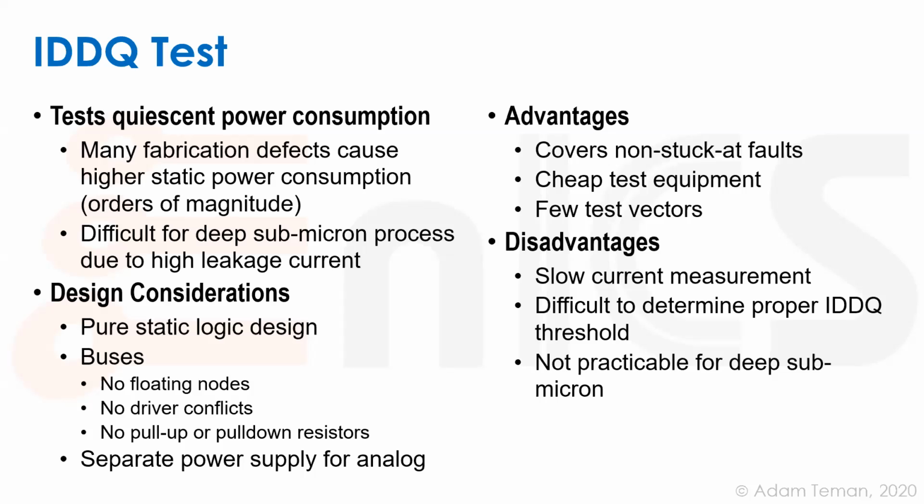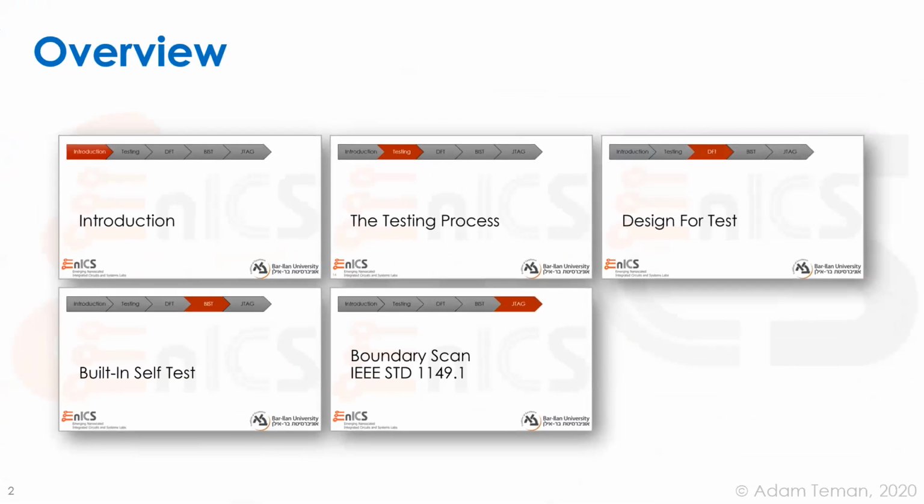You need to guarantee that you have a mode where nothing is toggling in the design. Once you have this mode, you can do the IDDQ. You can disable all the clocks. All the clocking is controllable, and the PLLs are not running and so on, and then you can measure your static power. That's, I think, the basic. It shows you if you have a short, basically. Yeah, that's the basic requirement to make sure that you don't have a big leakage or a short.